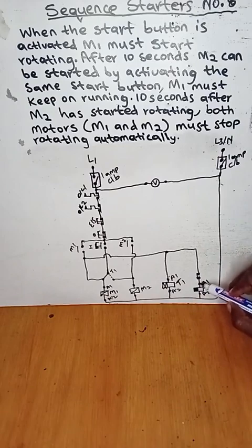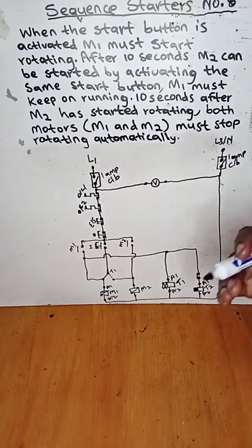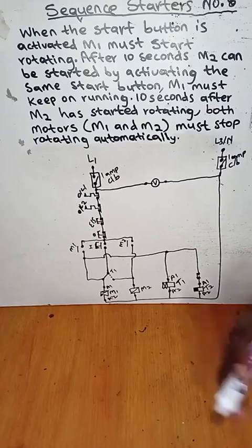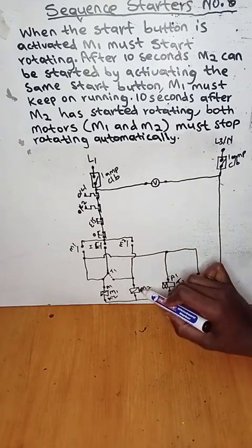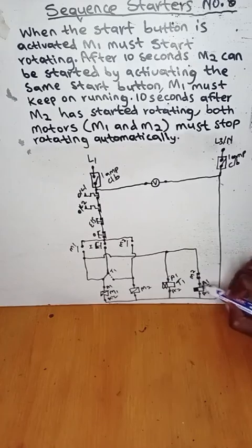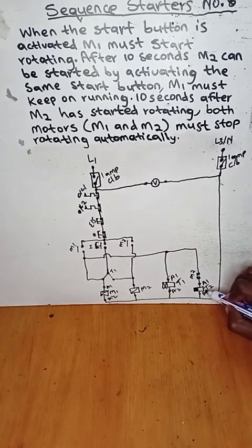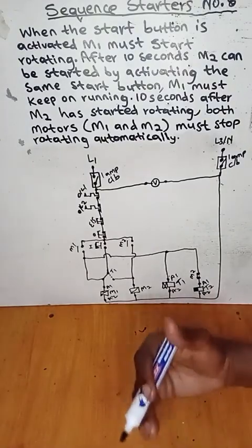So this contact must be the contact of motor 2, because the coil of delay on timer must start counting after the coil of motor 2 is energized. So when the coil of motor 2 is energized, it will affect this contact to be open, so that it will affect the delay on timer to be off, so that it can start counting and affect its contact, right?